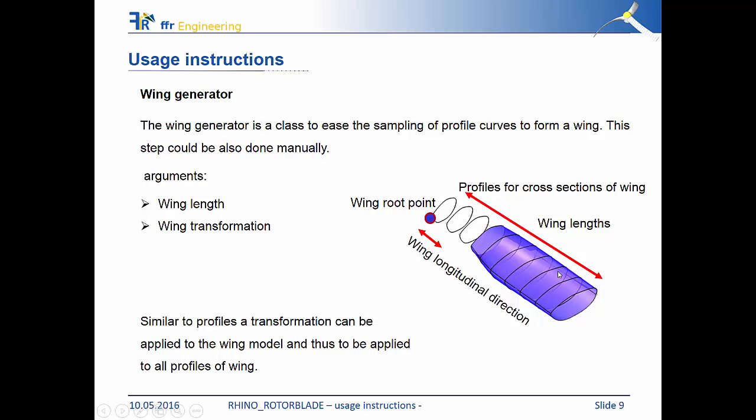I guess this is what you want if you do, for example, finite element analysis or something else. You need a surface model, maybe even a solid model, but a start for that is a surface model, since Rhino is a BREP modeler, and thus you produce a model using different cross sections. Of course, it's then important that you make something sensible by adding the cross sections. You can also make something invalid here.